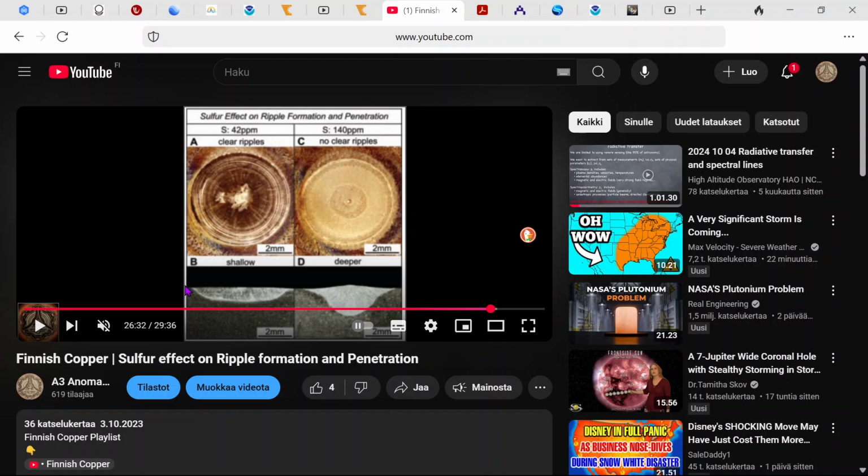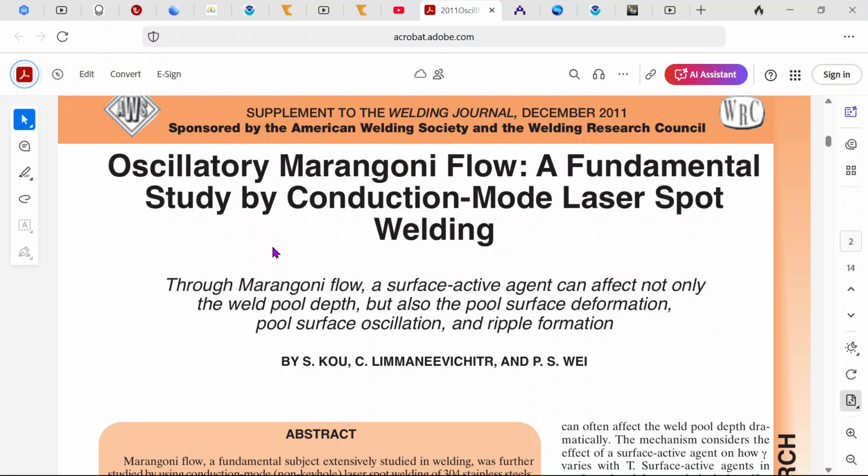Because in one of my videos I have been talking about the sulfur effect on ripple formation and penetration. And this is about welding. And I think somewhere should be: oscillatory Marangoni flow, a fundamental study by conduction mode laser spot welding. Through Marangoni flow, a surface active agent can affect not only the weld pool depth, but also the pool surface deformation, pool surface oscillation, and ripple formation. Maybe the weld pool depth is the most important thing in this case.